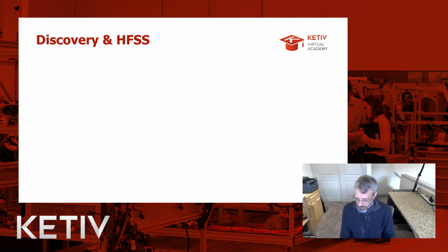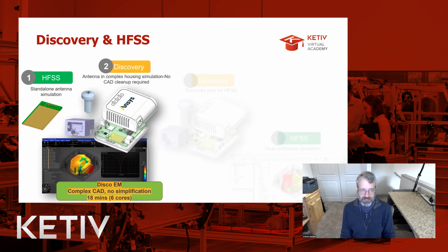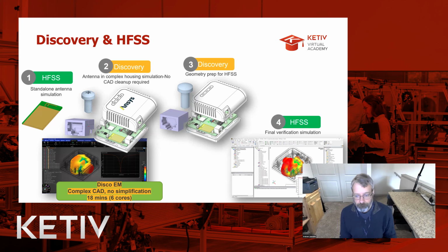So as we are thinking about our initial design task and we're getting started and we say, okay, we have an antenna and we want to do X. One of the new options that Ansys has is called Discovery for doing some of these preliminary analyses. So we might start with HFSS and do some standalone antenna simulation. But Discovery will also allow us to do rapid, but not necessarily the most precise analyses, to do very quick and dirty analyses, essentially in terms of if I have a complex housing and how is that going to impact my antenna pattern. We can do some analyses in Discovery to get a preliminary idea of how all that would work. And then, of course, we come back to HFSS for final verification simulation and higher fidelity.